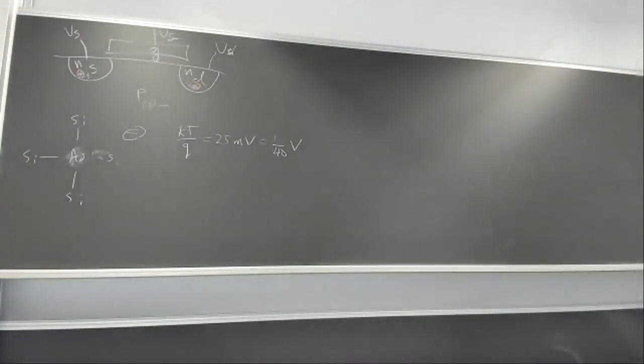Just think of it like a bubble in water. In this case, it's a positively charged bubble in this cloud of particles that are free to move. And quantum mechanically, it acts just like an electron, although it has a higher effective mass, so it gets accelerated more slowly by an electric field, like 2 times slower than an electron. But it's just a bubble. It's not a physical particle, but it acts like it in terms of the semiconductor.